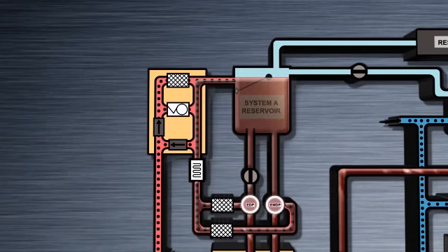The electric pumps generate a lot of heat and are cooled by hydraulic fluid passing through them. Because the electric pumps rely on the heat exchange process in the fuel tanks to keep cool, they should not be run on the ground if there is less than 1,675 pounds of fuel in the related tank. Despite the cooling system in place for the electric pumps, there is still potential for overheating. Temperature switches downstream of the electric pumps in the case drain line monitor the hydraulic fluid for overheat. The amber overheat lights above each electric pump switch illuminate when these sensors detect an overheat condition.